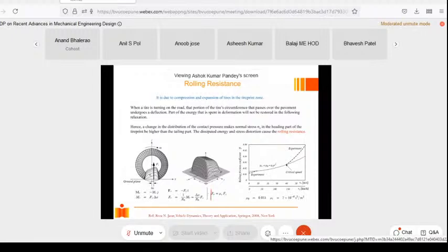And this is how basically the rolling component varies. Let us say the rolling force is equal to mu r times Fz, so again it is a function of normal load. So here you can see that it varies like this. As you increase the speed of your vehicle, your resistance increases, right? And after some time, which we call the critical speed, it increases exponentially. Initially it is approximately linear, and then it increases exponentially. So this speed we call the critical speed. If you might have driven your bike, when it crosses some speed, you will see that the front wheel starts oscillating. Wobbling of the wheel starts happening, and that is precisely because of these effects that happen at higher speed.